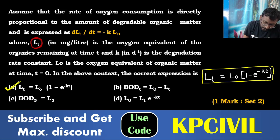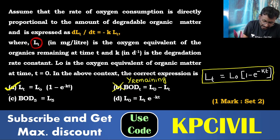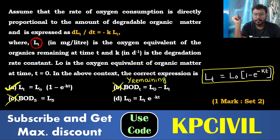Then what about the second one? BOD at time t is equal to L0 minus Lt. Is it L0 minus Lt? No. This is BOD remaining. L0 minus Lt is representing BOD remaining. This is not the answer. BOD5 is equal to L5? No. Organic matter remaining is L5. BOD consumed is BOD5. So again, this is also not possible.